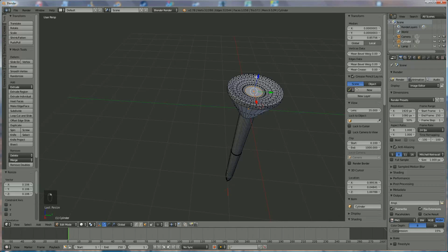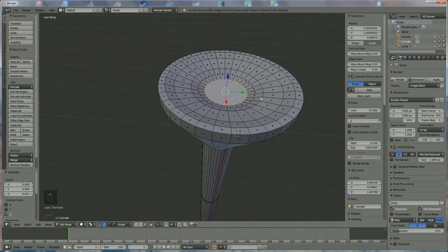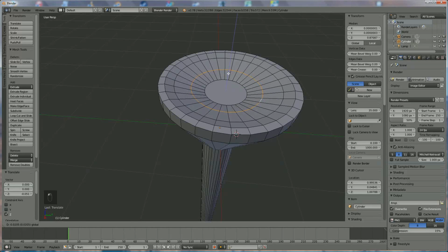Okay, now we're going to add a few extra things because I want the inside looking rather smooth, so we're going to select that one and we're going to bring it a little further deeper. If you did it already, you don't have to do it. To reselect, click on edge selection tool, click on the edge, hold down the alt button, click on the other edge and bring it down a little bit.